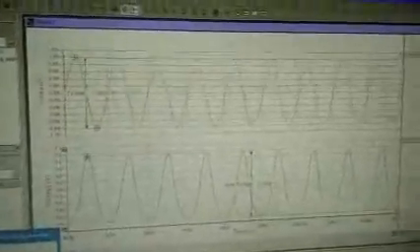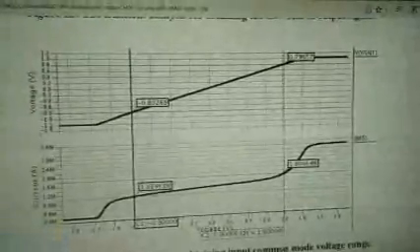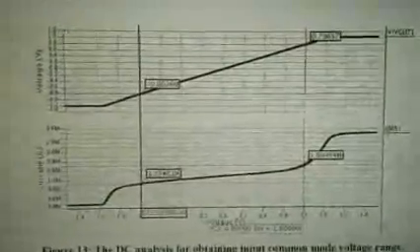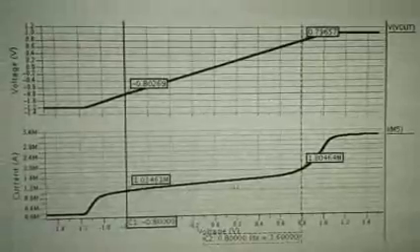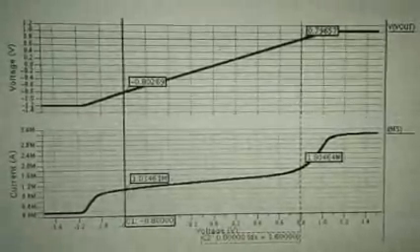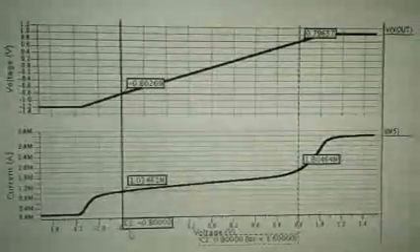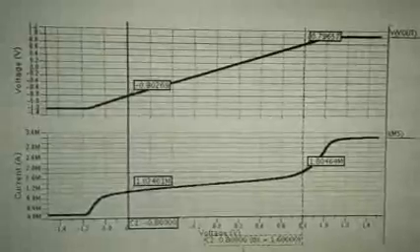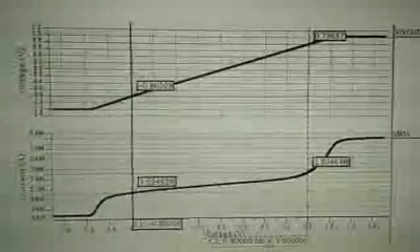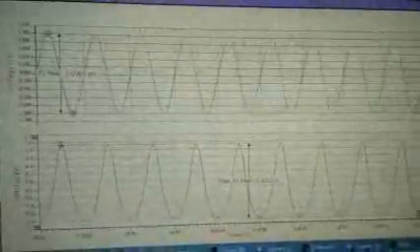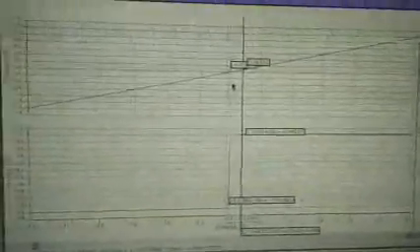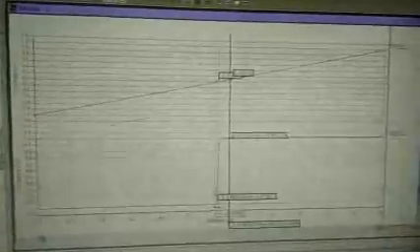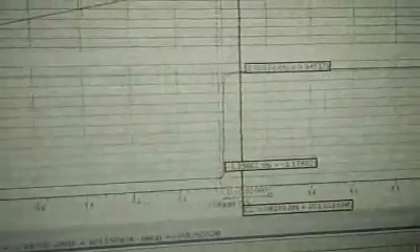After that, we will run through the input common mode voltage range simulation, and this is the result that we get. Here we can see that the current at M5 is almost constant. The result that we get for the minimum input common mode voltage is negative 0.8 volt, while the maximum input common mode voltage is 0.8 volt. Lastly, we will run through the differential output voltage swing simulation. From here we can see that when we apply a very small input signal, we will have a very large output voltage swing for the differential.